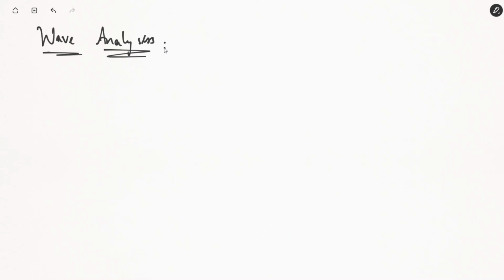So say for example your fundamental frequency is 50 hertz, then you will have another sinusoidal waveform of 100 hertz, with a lesser magnitude. Fine. So you'll have another sinusoidal waveform with a lesser amplitude that will cause the distortion of your sinusoidal waveform.